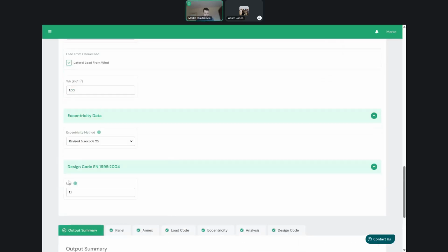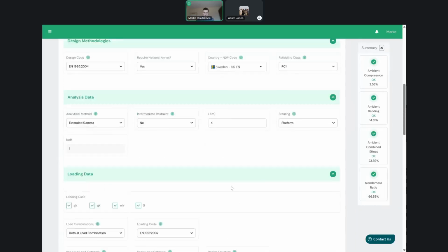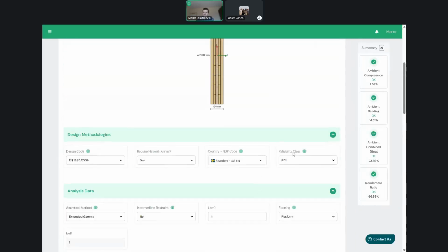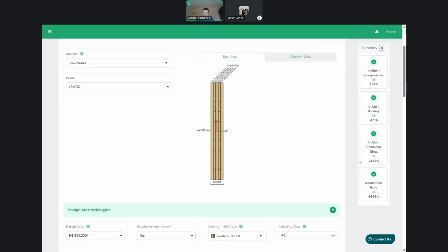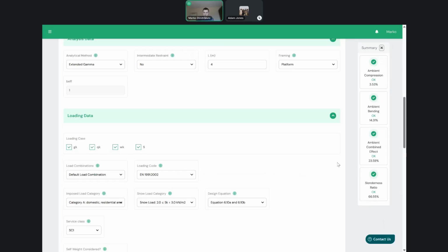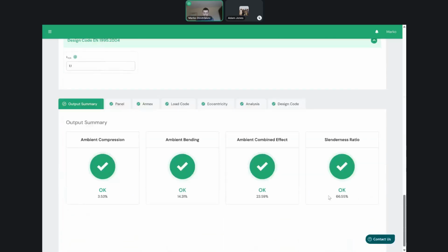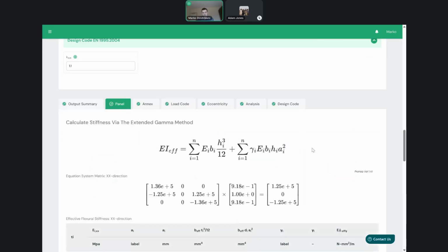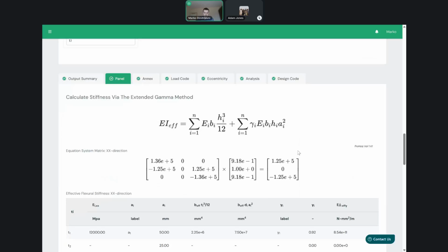The cases can be maintained as 1.1. In terms of the preview of the results, we can see that in this case we have all the checks performed, and the utilization is around 66-67%, governed by the slenderness. Concerning the fire design, we won't optimize this section anymore, even though we can probably go with an even lower cross section, but we'll briefly go through the results and proceed to the fire design afterwards.